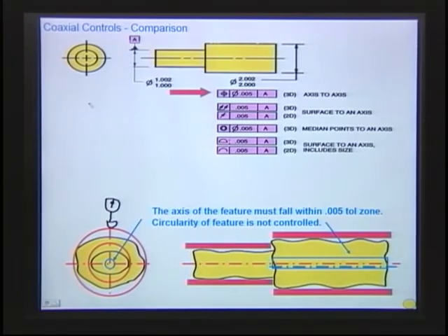Now, really think about it. Remember, when you're doing this, it could be position. If I have a diameter that looks like this and a diameter that looks like this, they're both oval, but they could have perfect position, right? So you could have two ovals that went oval within the size tolerance, because I'm going to take the smallest cylinder around one and the smallest cylinder around the other, and you say axis to axis, they're perfect. If they were to check something like this, they might do it with an indicator. Let's say there's your datum axis, and they might hold it in a collar or chuck, and let's say this is our diameter, and the diameter is off center like this. You see how much the diameter is off center, and let's say the center is off by 0.0025.